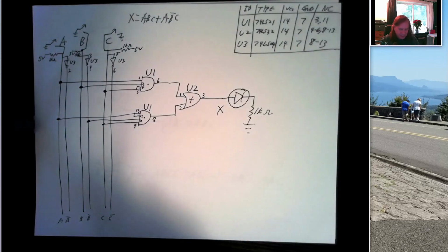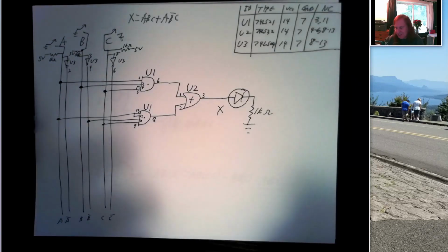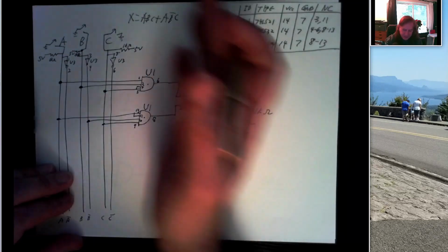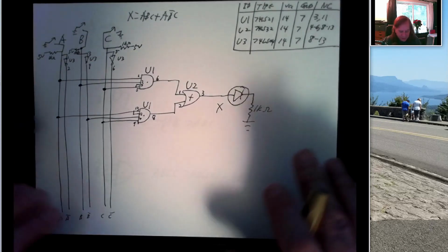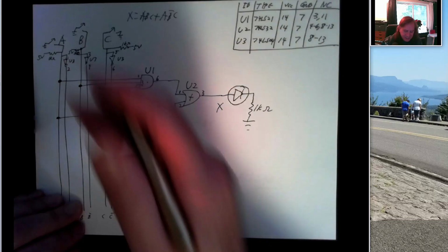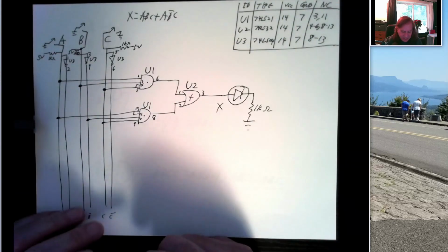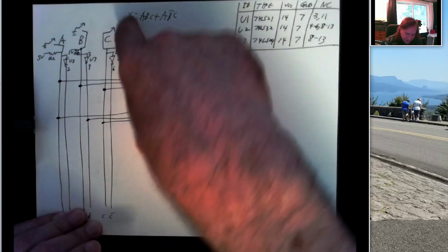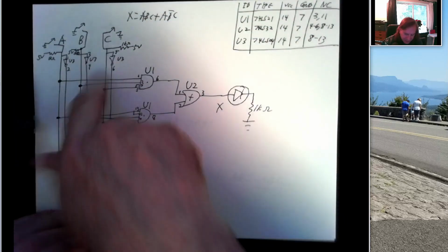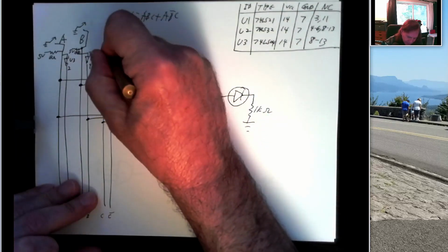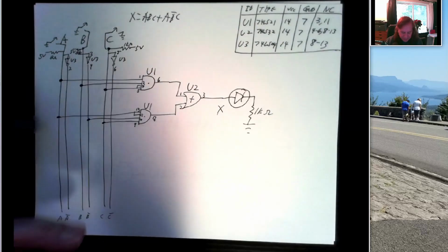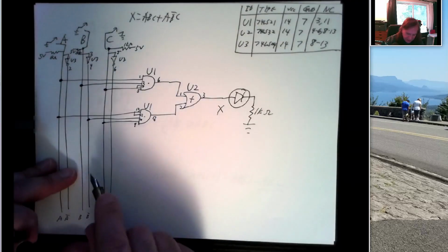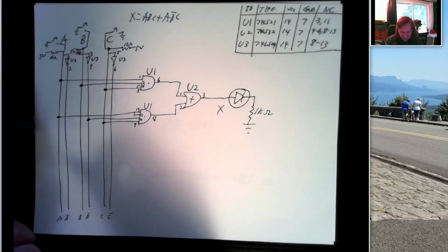So this is horribly sloppy at this point, right? But like I say, you do this part of it on scratch paper first, and then you draw it more neatly. But this has the required ideas, right? So C is controlled by a switch. If I close this switch, I'll get a 0 right at this point. If I open the switch, I'll get a logic 1 at this point. And then, you know, this is C bar, and so on.